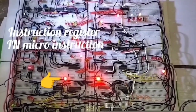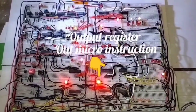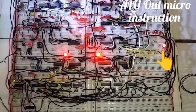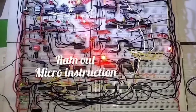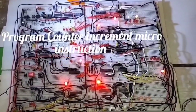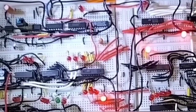Now please observe the execution of the instruction load B. First see all the micro instructions I labeled on the breadboard computer. Initially the step counter is 0 and the instruction is also 0. This is the reset value of the breadboard computer. When we press reset, the A register, B register, program counter, and instruction register will all reset to 0.